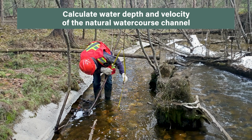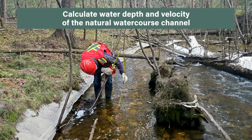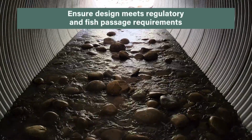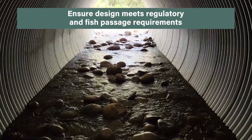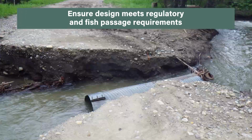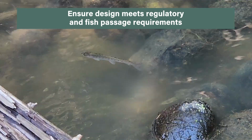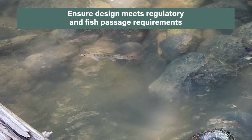Use hydraulic analysis methods to do these calculations. The process may need to be repeated to find a suitable structure size. Ensure the design of the watercourse crossing structure meets regulatory and fish passage requirements to avoid crossing failure or road washout during high flows, and to allow fish to pass across the life cycle of the structure.